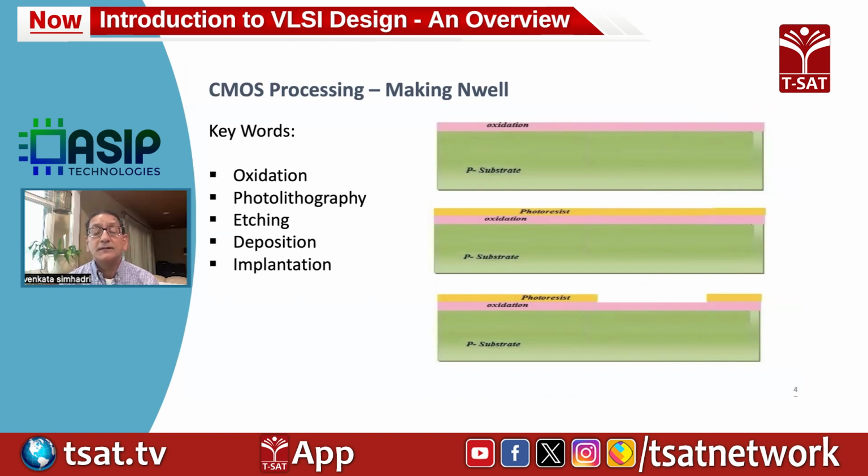You grow a layer of silicon dioxide on the wafer, which is used as insulation between the transistors, and silicon dioxide is also used as a gate material. When you have a gate that has silicon dioxide and polysilicon on it, that will be used to power on and off a transistor.